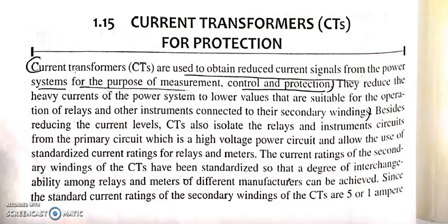So this means whatever current transformer we have designed should be able to reproduce the required current in the secondary in proportion to the primary value. Whatever instruments we connect on the secondary side, and whatever value the current transformer produces, it should be in the ratio proportionate to your primary value. Okay, so CTs are required for metering as well as instrumentation purposes, and they should be accurate over the normal working range of currents.